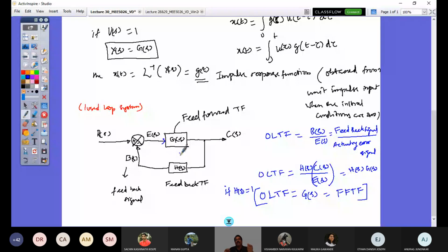But when I give my steering input, it is not going to happen immediately. It will have to pass that time of transient duration. So when it attains its steady state, what does that mean? Whatever input I give, that same would be the output response, right? My intention is, what is that input? My wheel should have a steering angle turn at the interaction of the road. Appropriately, I give my steering wheel rotation, and that angle should be maintained to go in a car if my vehicle is a neutral steer vehicle. So that is steady state.